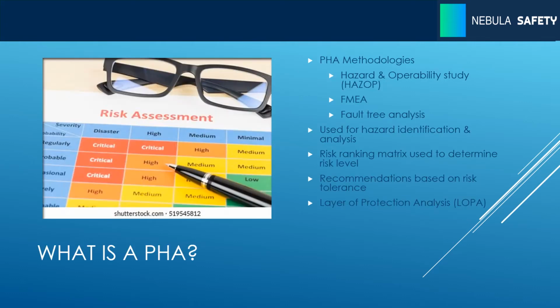As I mentioned in my introduction, there are several different PHA methodologies that can be used, and different PHA methodologies work better for different processes. So as I mentioned, I am specifically focusing today on an overview of HAZOP and LOPA, but there are other methodologies, the FMEA, the Failure Modes and Effects Analysis, the Overpressure Risk Assessment, which is used to meet CAN/CSA-Z767 requirements in Canada.